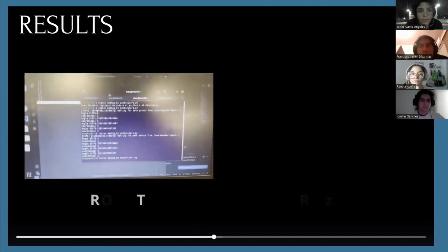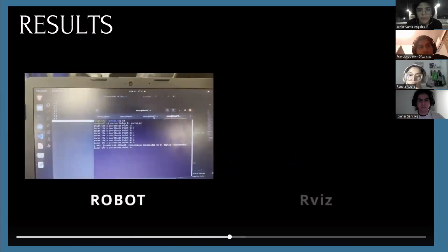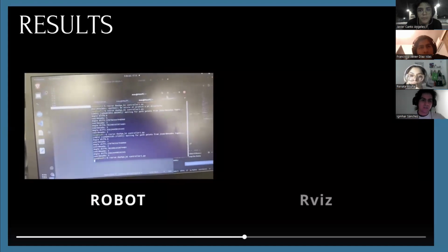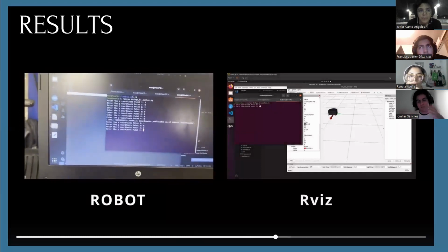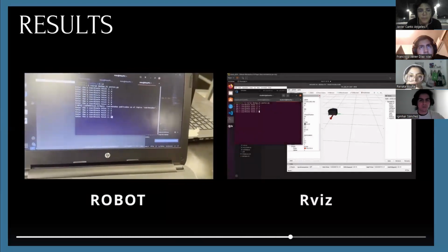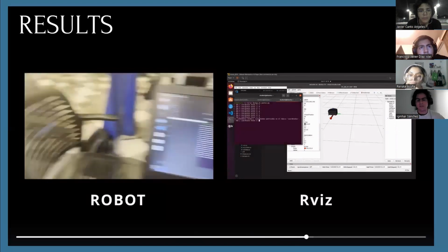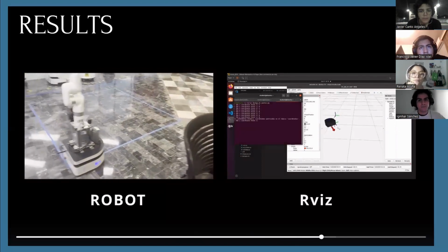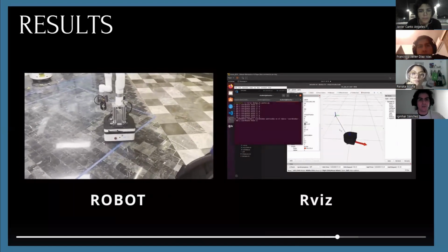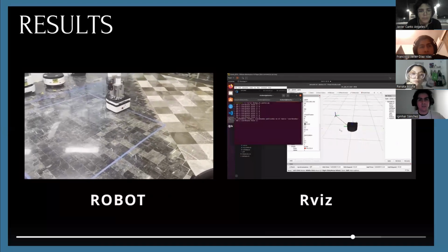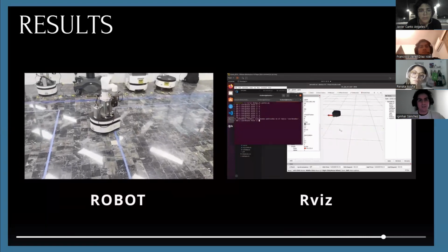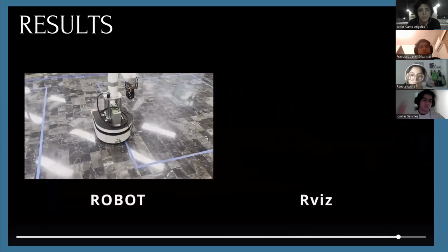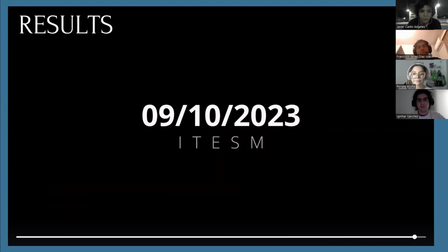On the irregular video, where we needed to do the path generation, I also had a set point where I put all my points. On a 2 by 2 square, the same as the square trajectory, I put four points, X and Y. The ROS simulation started first, and as you can see, it made the same trajectory, but with a bit of an offset on this path. That is because of the open loop controller. If it were a closed loop controller, it would be precise.